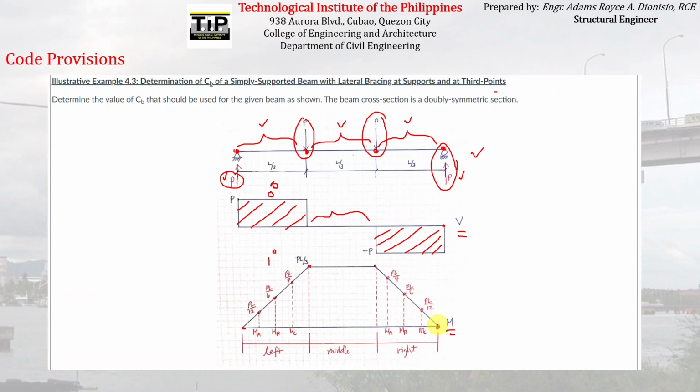That will verify that your answer, or your diagram, is correct, since there is no moment at the other support, at the roller support. So therefore, the corresponding bending moment must be equal to 0. So the corresponding moment diagram and shear diagram will be equal to this.